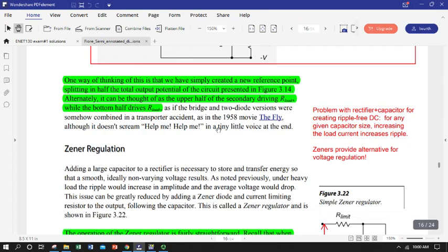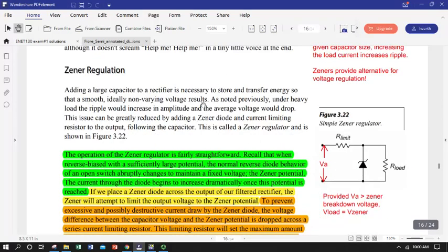The only significantly new concept that we have with rectification is an additional nuance into smoothing, and that's using a Zener diode plus a capacitor instead of just a capacitor by itself. So that's actually taking advantage of two different diode functions in one. Your rectifying diodes basically give you a single polarity pulse DC, and then the Zener and the capacitor work together to give you beautiful smoothing and give you true DC and really reduce your ripple.